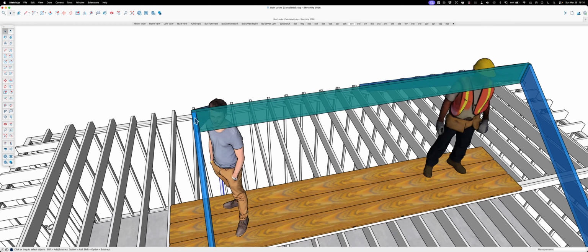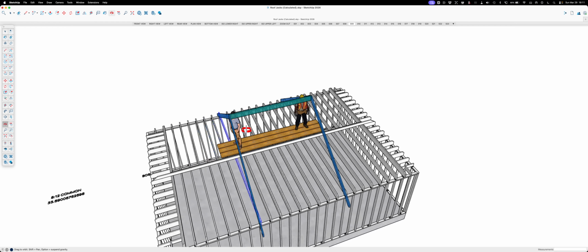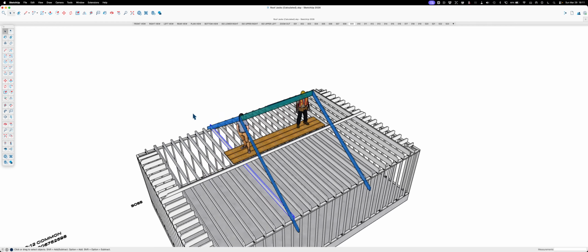And so that way I'm not toenailing through the rafter into the ridge. I'm back face nailing from the opposite side of the ridge. And this is what we call the initial skeleton, because once this is all nailed off, this can just freestand. And this is helpful so that we know where everything's going to be going.